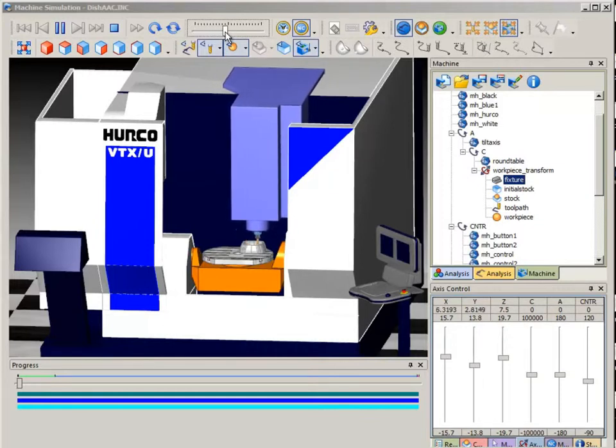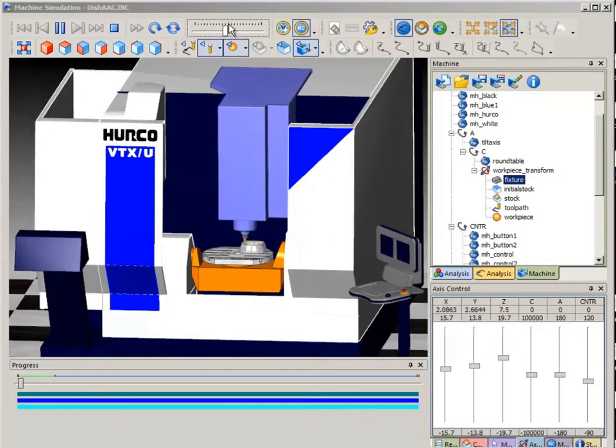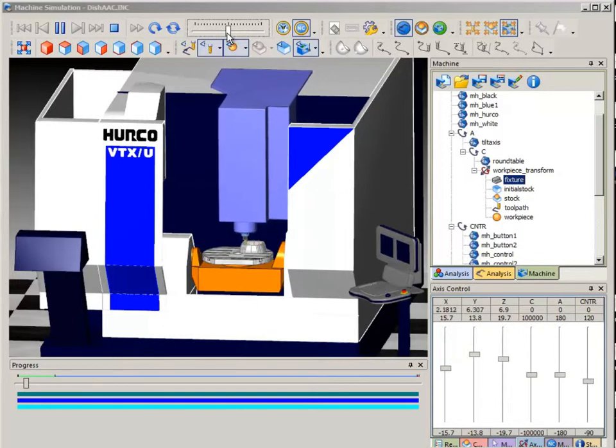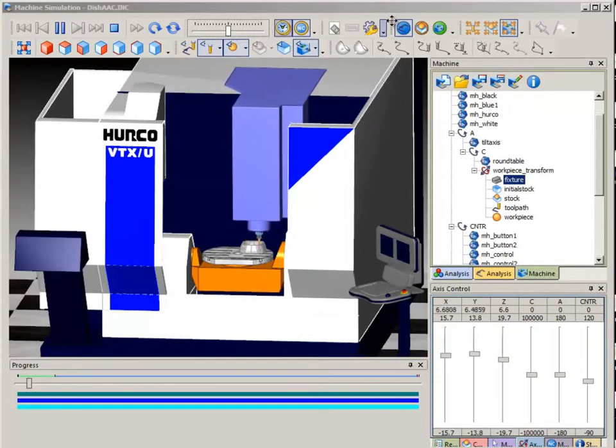to increase in speed. If you move past the midpoint of the slider to the right side, it will cause the simulation to jump. What it will be doing in this situation is reading multiple moves of the toolpath and processing them and then updating the screen, instead of processing every single record and displaying it right after each record is processed. You also have the ability to run simulation in Toolpath mode,